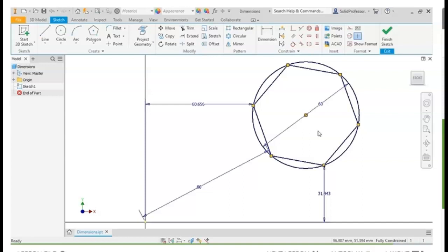It's generally considered good practice to ensure that every sketch you create is fully constrained before moving on to create features. And using dimensions is the most straightforward and rigid way to do this. In the next lesson, however, I'll show you another way to define sketch geometry by using constraints to control geometric relationships.